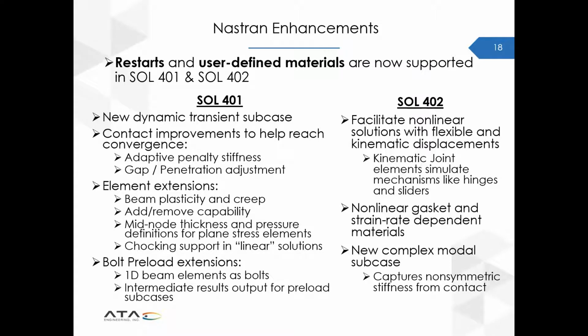as well as the support for user-defined materials. Now, looking more specifically for solution 401, we have a new dynamic transient subcase that allows for the simulation of vibration with nonlinear behavior, whether that's contact or large displacements or plasticity. In addition, there are some contact improvements. So these are aimed at improving convergence. So it includes 2 main things they've added this time.